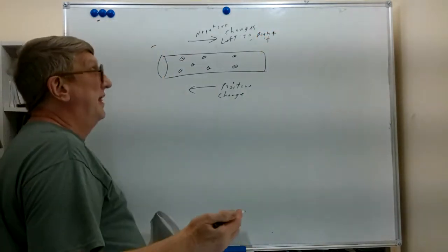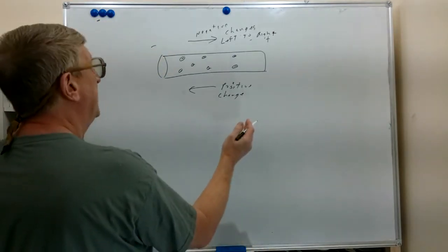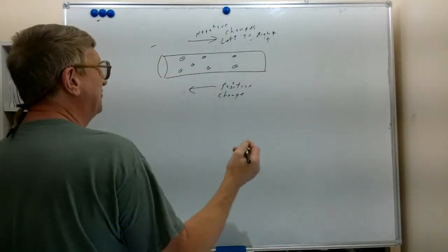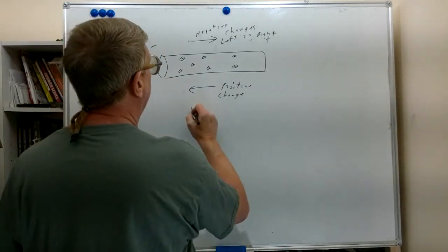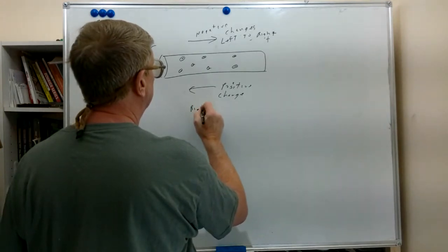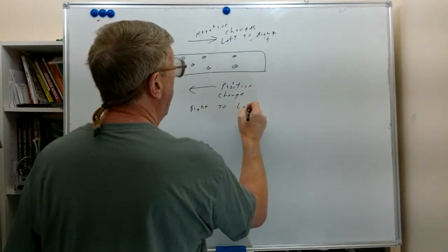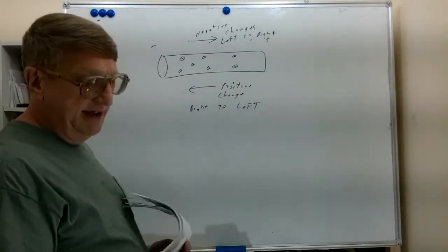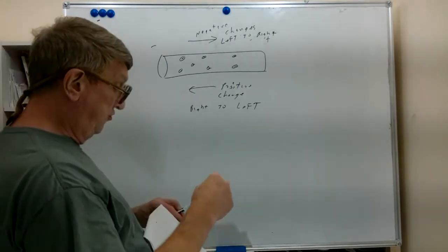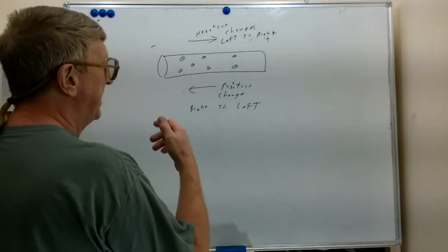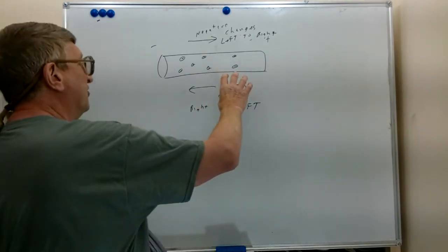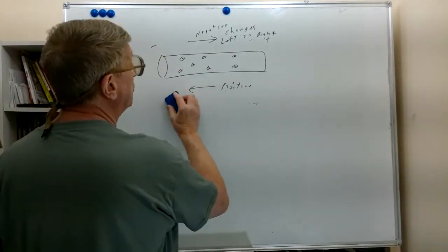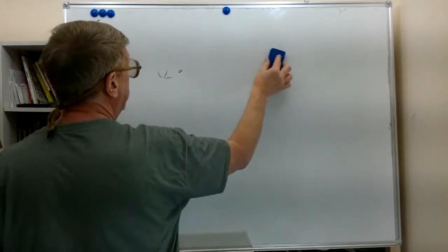Which is being carried by the electrons, where the positive charge is happening because electrons are leaving. So the positive charge is moving right to left, at the same rate that the negative charge is moving left to right. And we also noticed in our drawing just a few minutes ago that whether you think in terms of conventional current flow and positive charge, or electron flow and negative charge, your polarities across all your components in your circuit end up being the same.